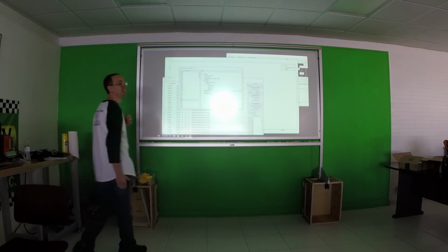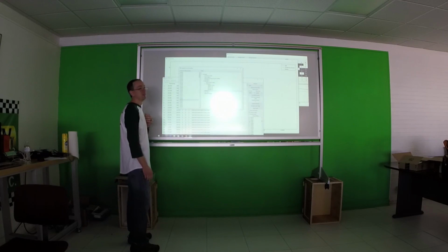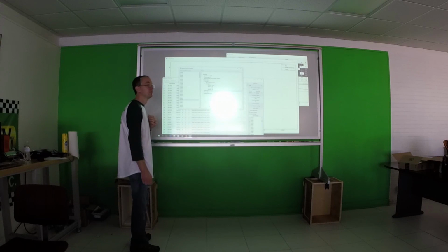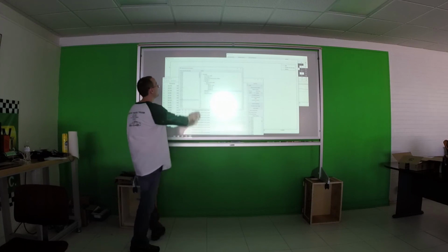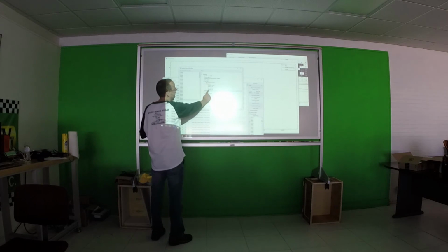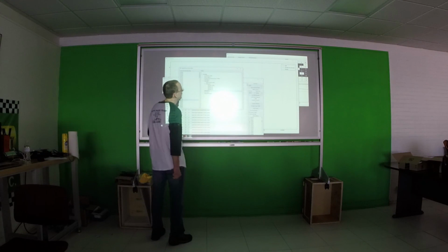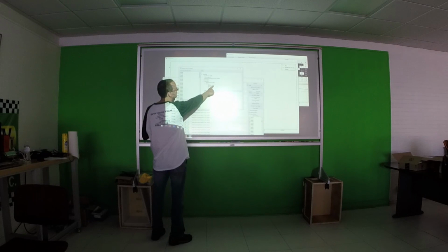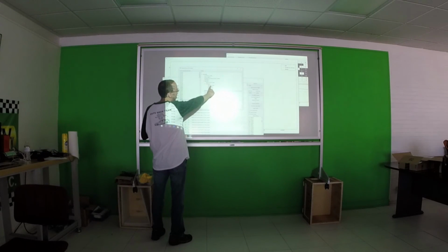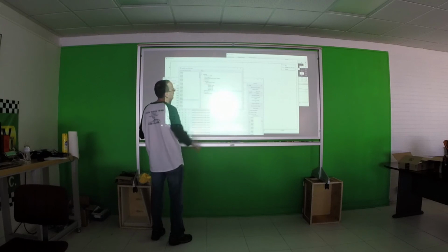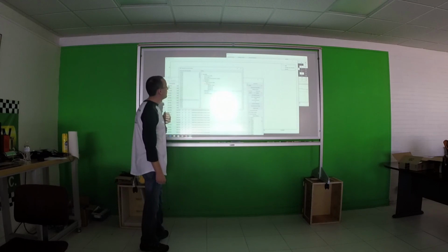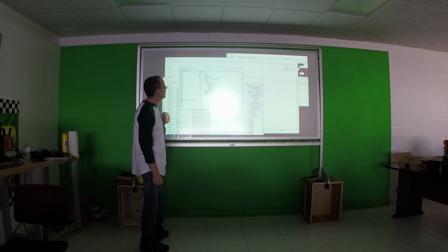This can't do that level of it. He had to manually work out how to do that. But for the rest of what we had to decode, this would have cut the time down to a tenth. You can see this is the byte that I said stores the gear. So if you were using this program, you can see most of the time the gear was not set. But when it did, you can see these set values. That tells us what values we would need to set to change gears.